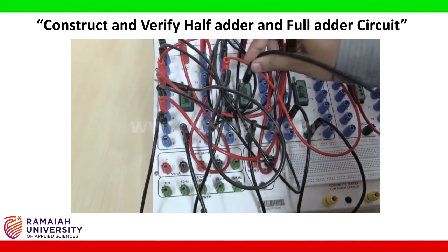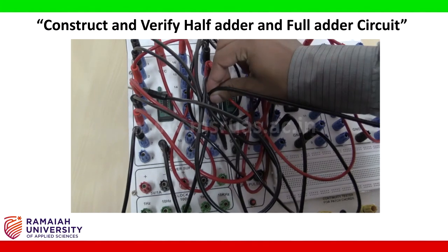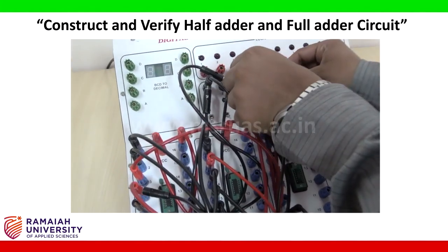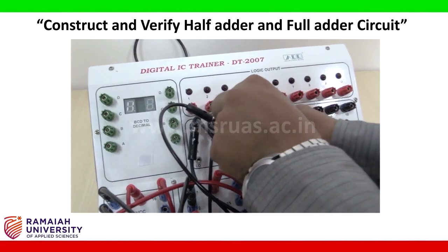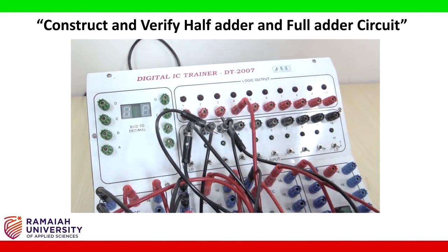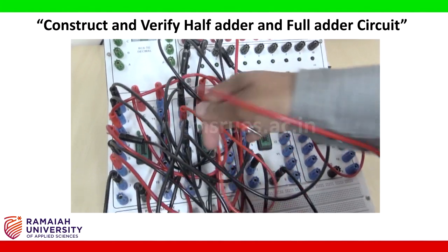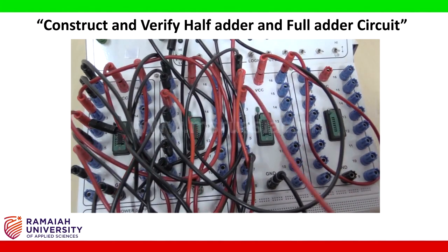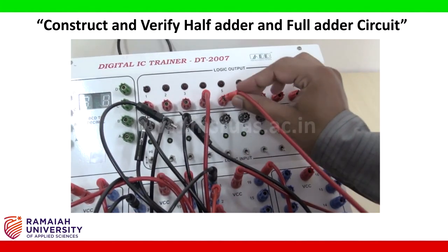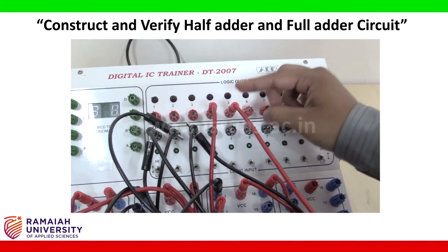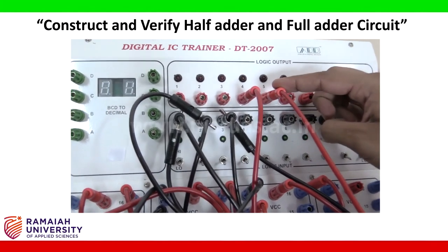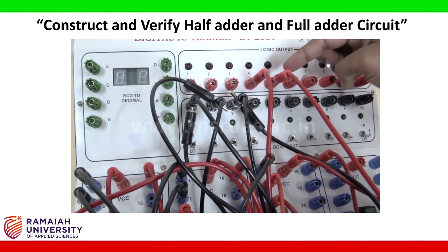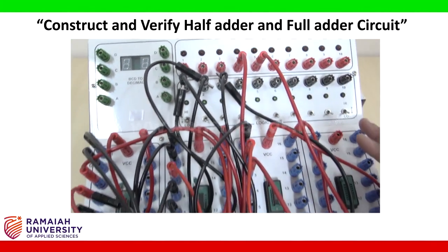Pin number 5 of AND gate is connected to carry in, that is here, input. And at last the output pin of AND gate, that is pin number 3, is connected as an output. I am connecting at the output knob, so this represents the carry. So there are 2 outputs, one is sum, one is carry. So this completes the connections.